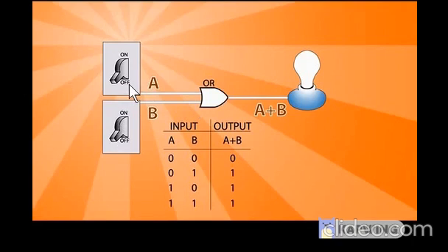So you may connect the two inputs of an OR gate to a thermistor and to a smoke detector. I hope you remember the smoke detector from the radioactivity chapter. One input is connected to the smoke detector and one to the thermistor. So if any input gets high, the fire alarm will start working, right? In that case we use the OR gate.